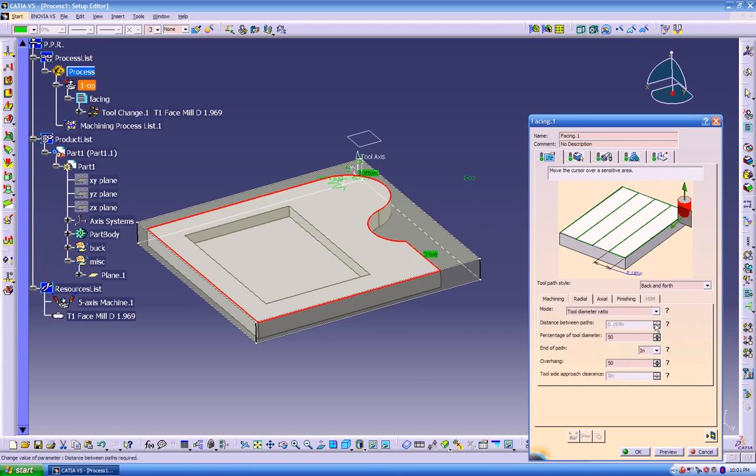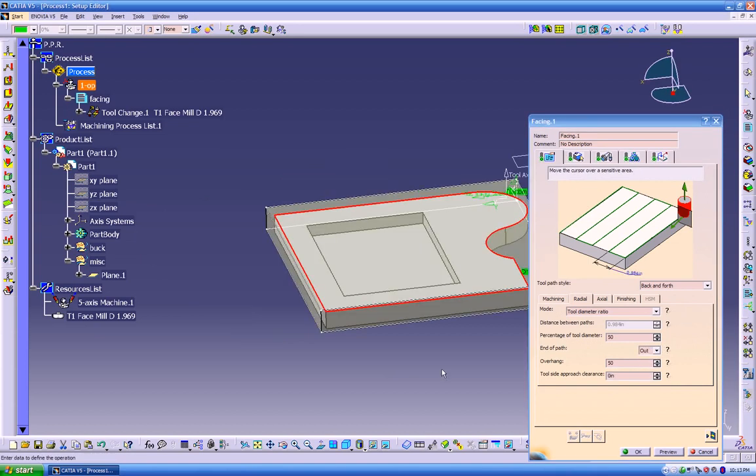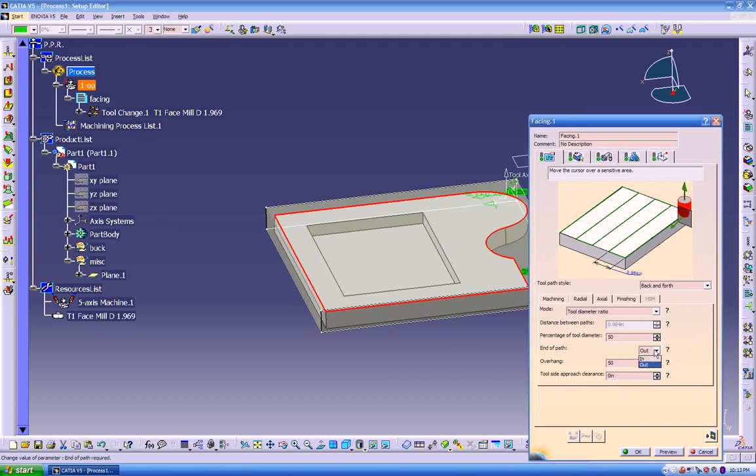and it's got one of those options in here. See over here, I think is when it's asking us how you want the tool to be right on the edge, or if you're going to go outside. So we turn this option on. Make sure the tool goes on the outside of the part. Now it's in.